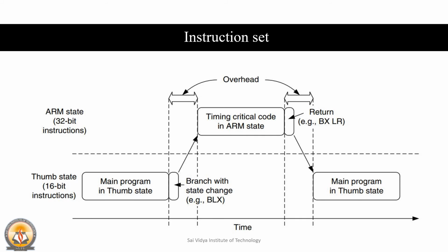ARM and Thumb codes might need to be compiled separately in different files, thus increasing the complexity of the software development, and it also reduces the maximum efficiency of the CPU core. With the Thumb-2 instruction set, it is possible to handle all the processing requirements in one operation state. Note that the Cortex-M3 processor does not support the ARM codes, and previously all the exceptions were handled in the ARM state of the microprocessors.